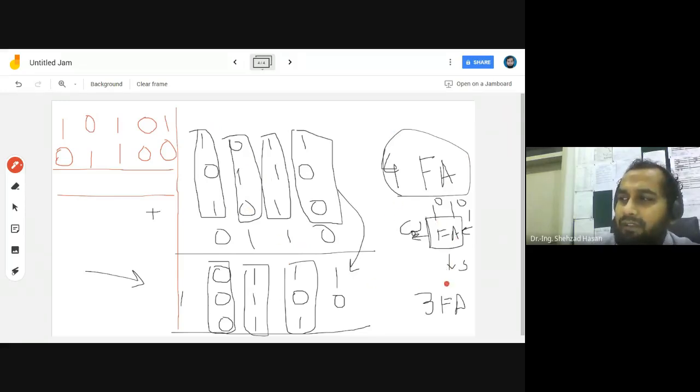So every full adder is a 3 to 2 reducer. So if you're going to give 3 inputs to it, it's going to reduce it into two bits. You're going to use 1 bit at this level, another level, and you're going to repeat it. Using just 7 full adders, what we have done is obtained this result. And at the end we need a 5-bit ripple carry adder or carry propagate adder, whatever you can have.